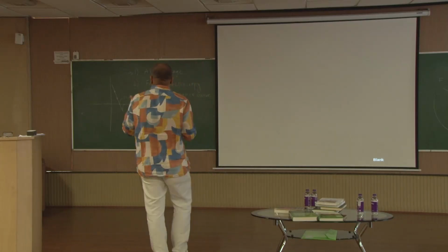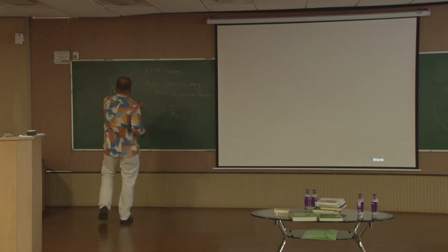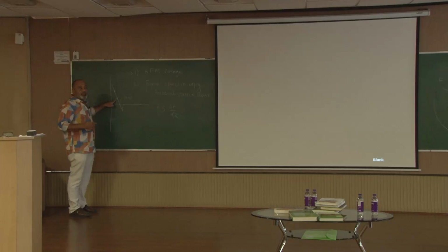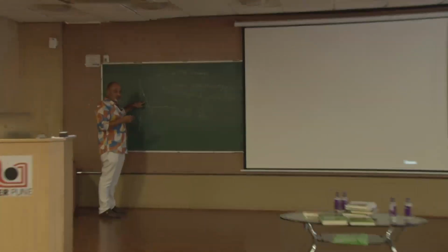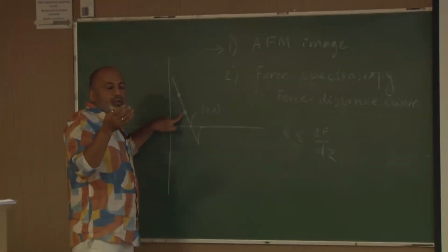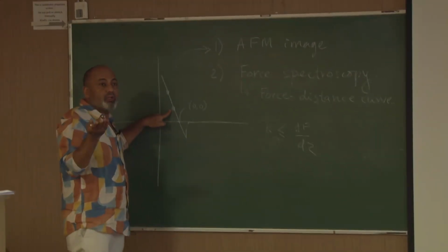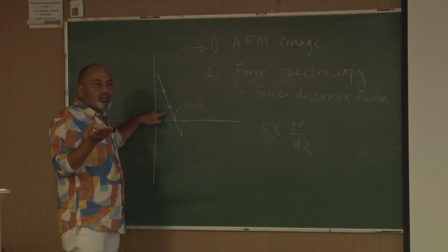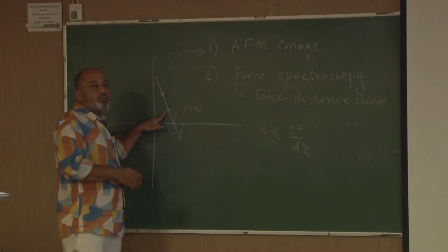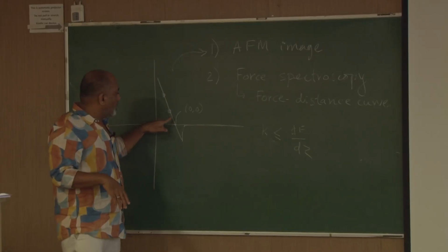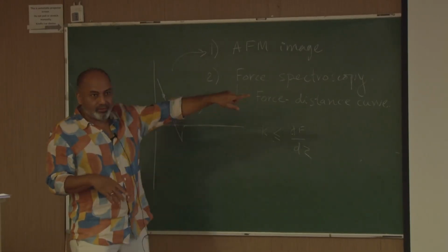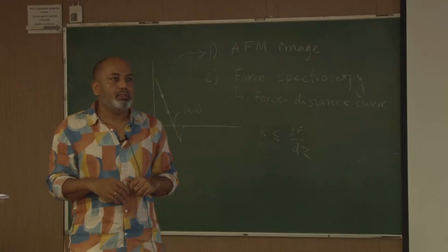Right. So, from the force curve, if I have pushed it up and my signal is 1.2 volts, and 1.2 corresponds to 1 volt, and 1 volt corresponds to 1 Newton, I hold it at 1 Newton. The same calibration curve will tell you, if I have to do this at 10 times less load, you will have another set point decided for it.